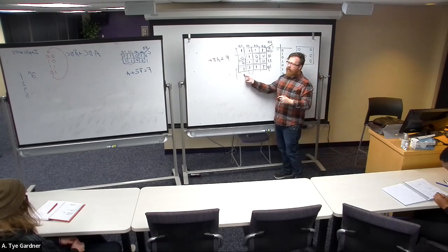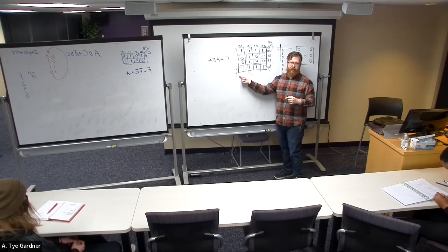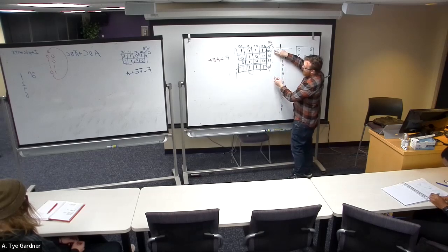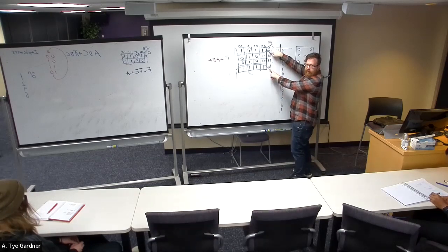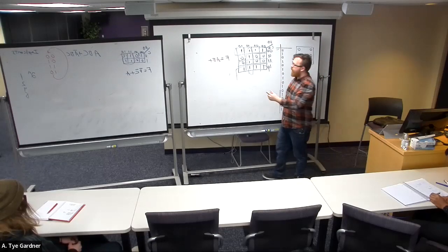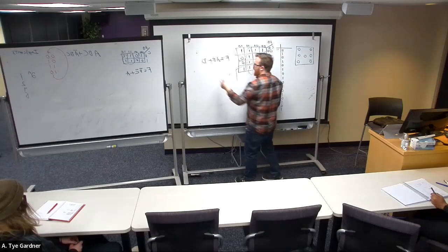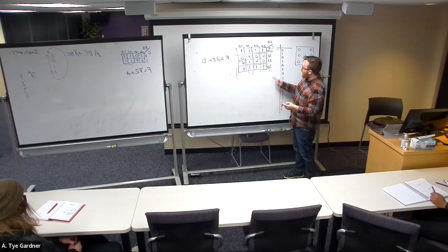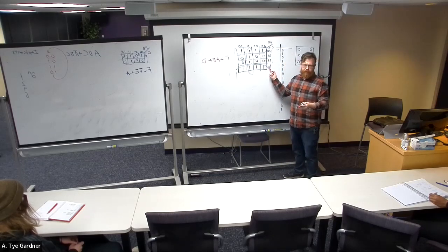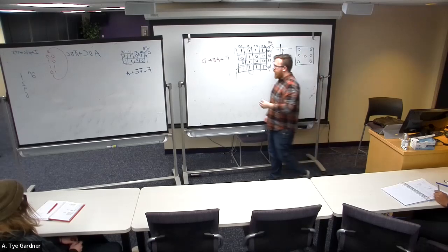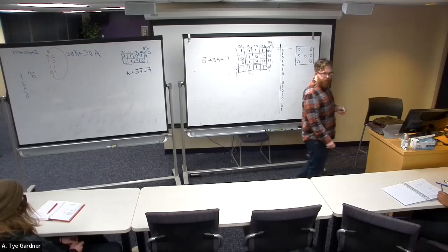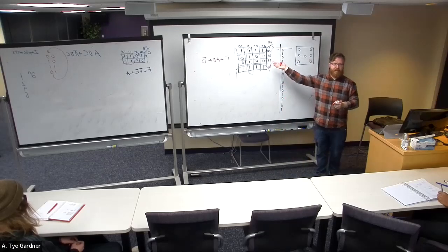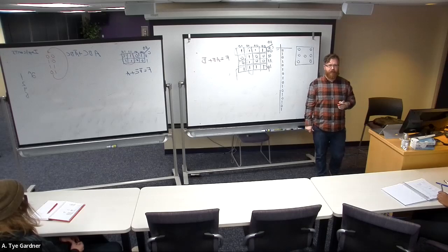Well, going across, if I go all the way across, that eliminates both A and B. Now, top to bottom is just a question: well, C does change, D doesn't. So we know the thing that changes goes away. Then we just ask the question, is D a 0 or a 1? D was a 0. It didn't change, so not D. Turns out that C doesn't matter to this. C is a useless input.